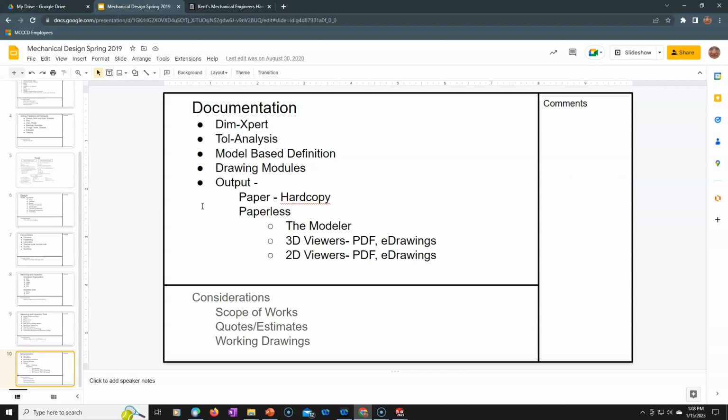When we sit down and actually do those tolerances, and in a lot of the drawing videos that I made, we talk about iterations. The first pass is creating the view. The second pass is applying the basic dimensions. The third pass is applying the tolerances. Fourth pass is, does it need to be geometrically toleranced to hold that geometry at a higher level.